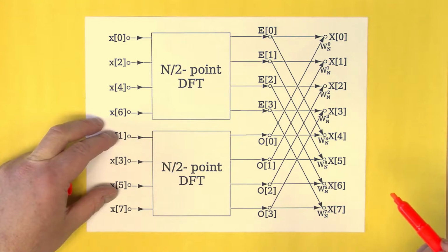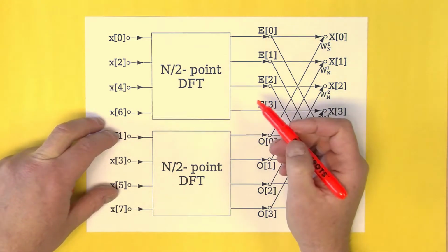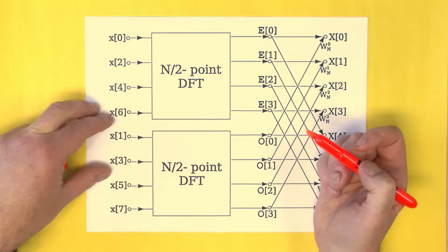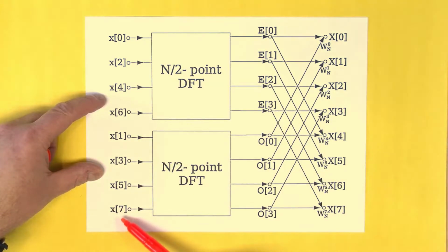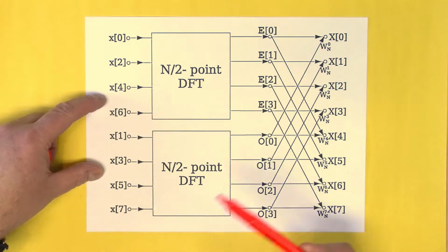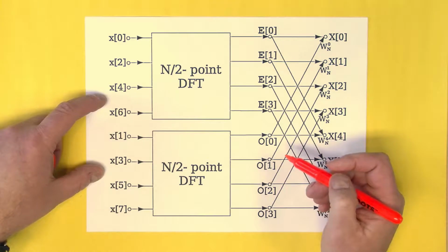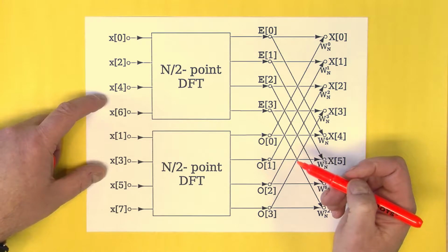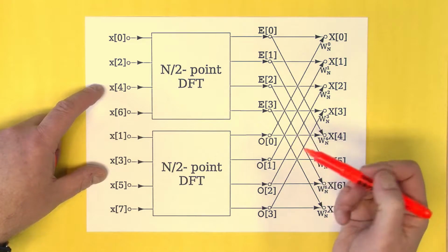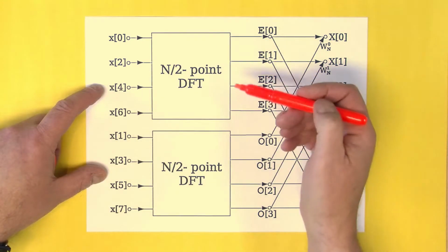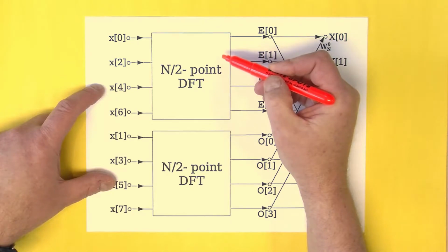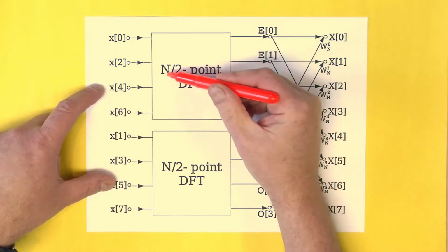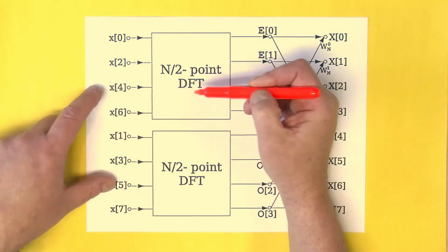And the way it does that is it actually takes an FFT, in this case they've shown one using 8 input samples of data, which would normally be 8 times 8 computations. And it turns out you can actually split it and do 2 half-size FFTs, which only have half as many points to deal with.